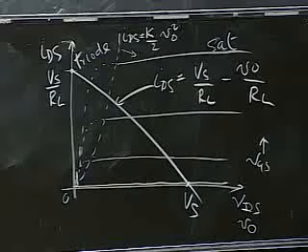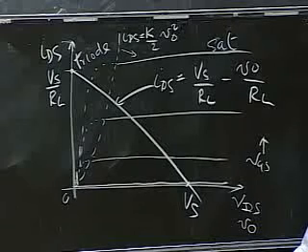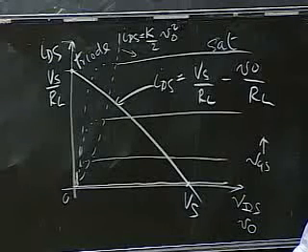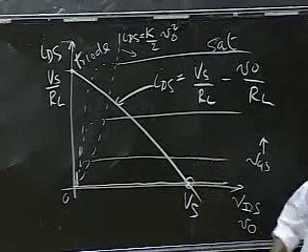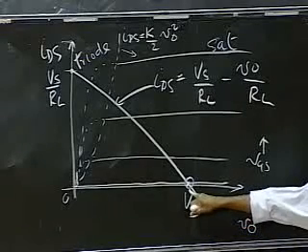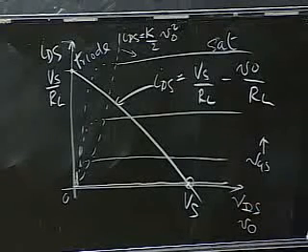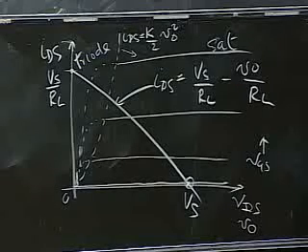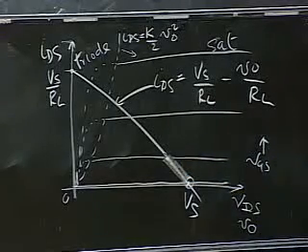Okay, so what are the 2 points here? I'll let you stare at it for a couple seconds yourselves to figure out what 2 points here bound the valid operating range of the MOSFET, or valid operating range of the circuit. Okay? So I'll start. One is this point, because at this point the output is VS. Okay, and VGS has just begun to equal VT. It's one, so think about where the second point is for valid operation. So it's here and somewhere along that load line.